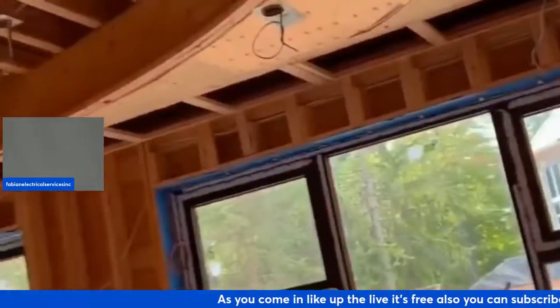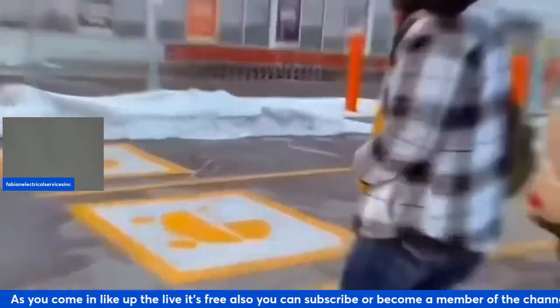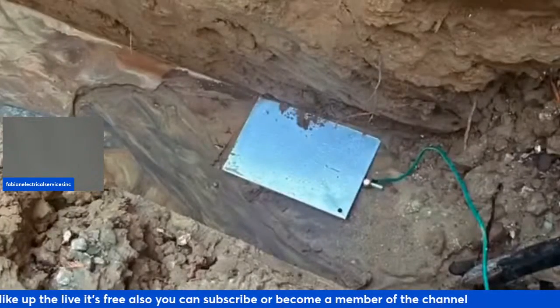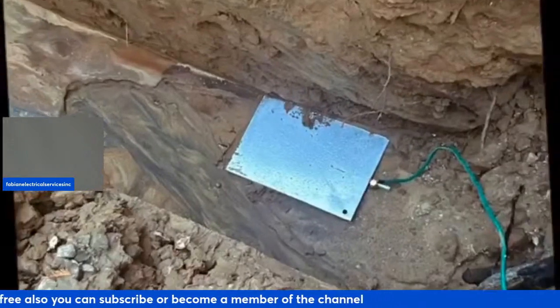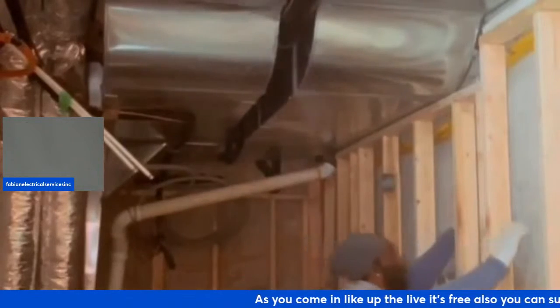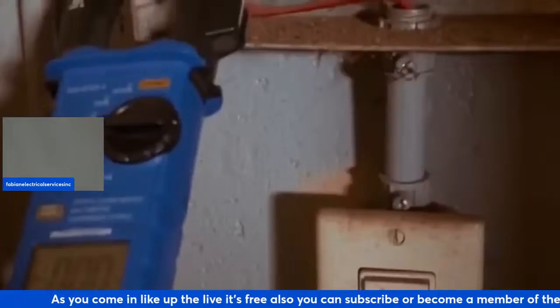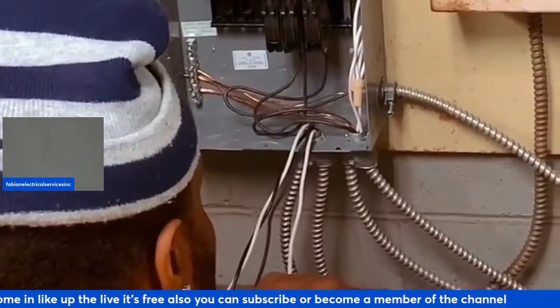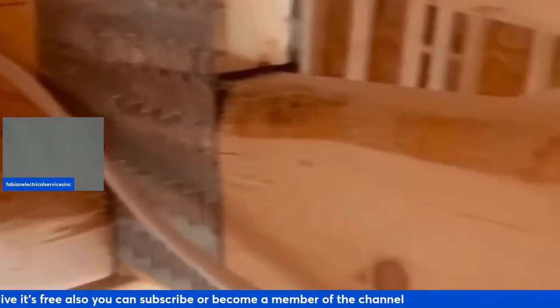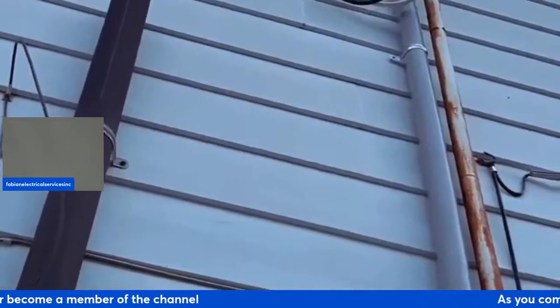Again, series arcing occurs when there's a break in a wire, causing electricity to jump across the gap, which can become very dangerous. Parallel arcing happens when electricity jumps from a damaged wire to another wire, like a neutral or ground. That's probably why sometimes you'll see what I believe is called dirty power.